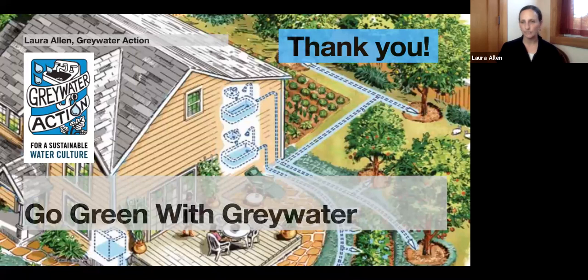If it's an advanced septic system, an advanced treatment system, those function very differently. And changing the ratio and the loading of that system could cause problems. So with that, you would want to talk to the designer and look at the new loading and how that impacts the advanced system. But if you have the tank and leach field, the conventional septic, removing Greywater is most likely going to improve the treatment of your system. Very cool.